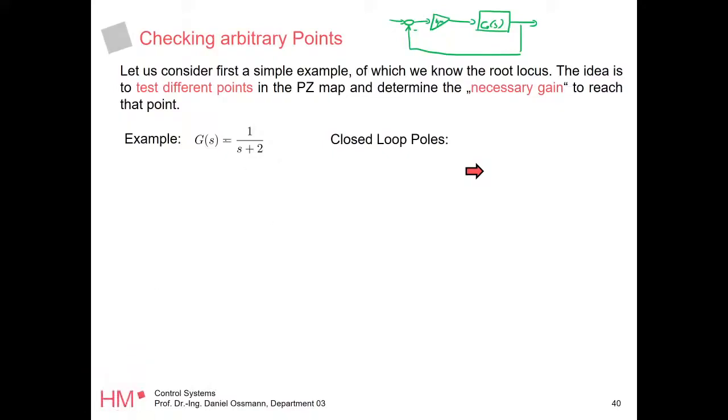Okay, so let's determine the closed loop poles, right? So let the closed loop poles again take the controller into account. So we need to take that into account as well. And we know that the closed loop poles are nothing but the numerator plus Kp times our denominator of that equation. If you plug that in, it's going to be S plus 2 plus Kp times 1, right? Because here's a 1, equals 0.